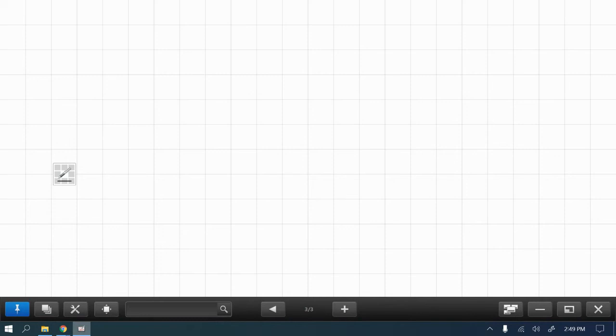And then you can understand, because you've had soils, whether something is gravelly or sand, or a clayey soil that's not plastic, or something that is plastic. And what does plastic mean? Remember? I had y'all go dig your own soil up. I told you to dig down the first inch or two and you got some gravelly sand, and then I had you dig down even farther to get clay, something that stuck together, so you knew it had some clay. So this would be like in situ.